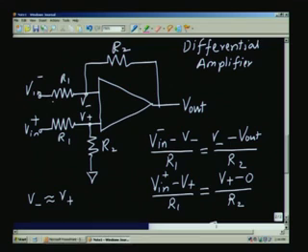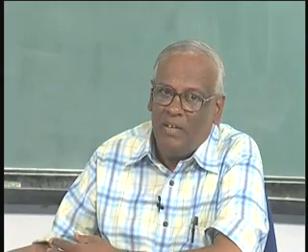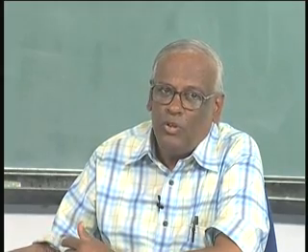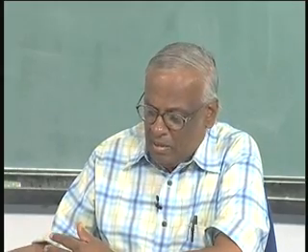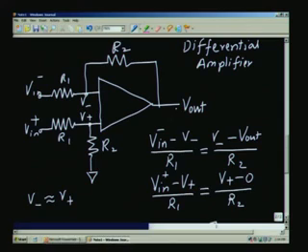That means it does not take any current from the sensor, but the output can give you sufficient current for driving some external circuit. So, sometimes we can simply have a unity gain amplifier which will give you a capability for supplying larger current, but not without loading the input or the sensor itself. So, these are some of the things which one can do.